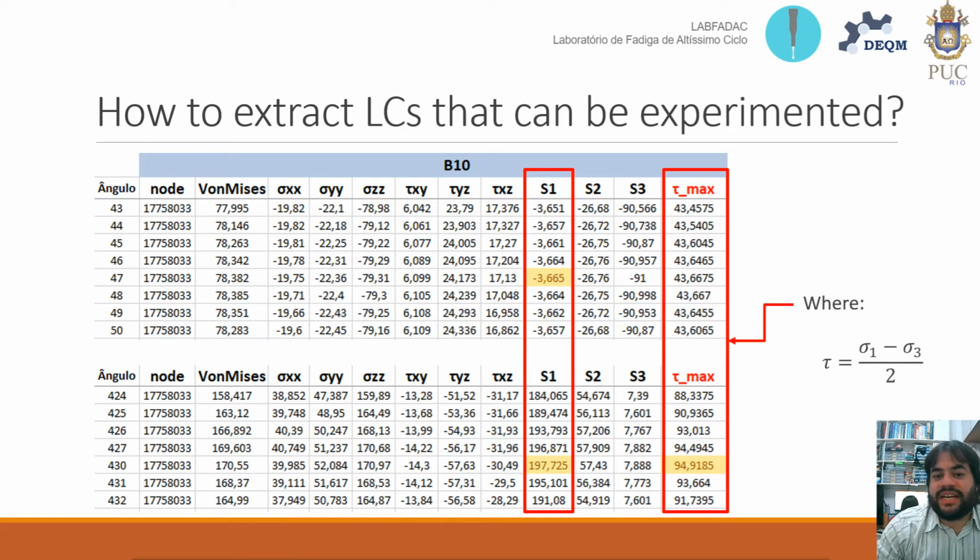Since well-established experiments reveal that the presence of a mean shear stress does not affect the fatigue life of a mechanical component when subjected to a very high cycle fatigue regime, and considering the fact that the design stresses are to be kept low enough to maintain the crankshaft within the elastic regime, it was decided to consider the maximum obtained value for shear and consider it equal to the shear stress amplitude.